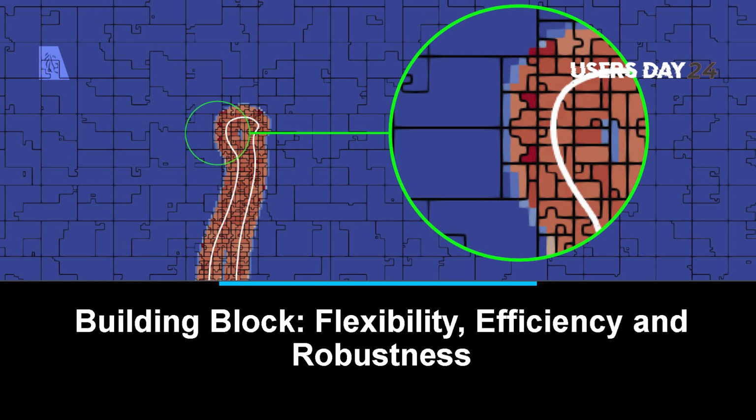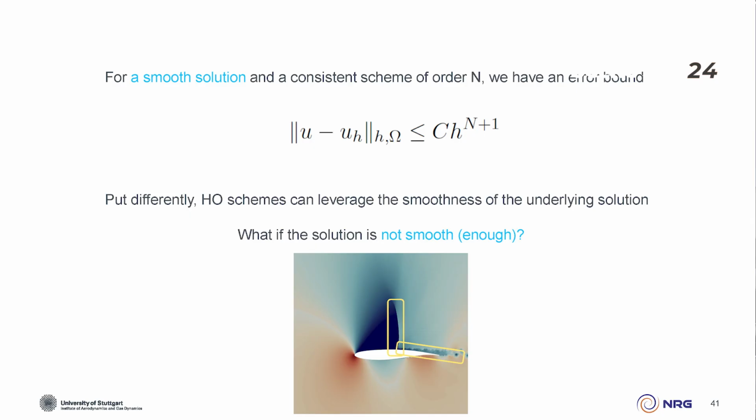They have favorable properties for compressible flows, advection-dominated problems, and they are great to parallelize from an HPC perspective because, let me go back, this idea means that most of the work is done by the local projection in an element, and the communication to the neighboring element is done weakly through a surface flux. So it has this nice property of having tons of local work, great for scaling, great for node level performance, and just very minimal communication. Okay, second building block.